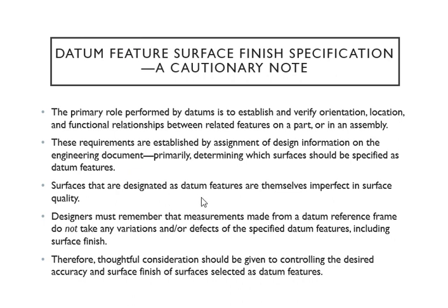And these surfaces that we give the datum features for, the surfaces that are designated as datum features, are imperfect in surface quality. Don't worry about this. It's just a daily thing. Just concentrate on the symbols of the datum feature, your control frame, and the information in the control frame. How are you gonna locate or orient? According to your three planes that are perpendicular to each other, you can correctly orient your part. If you get that much, I'll be very, very happy.